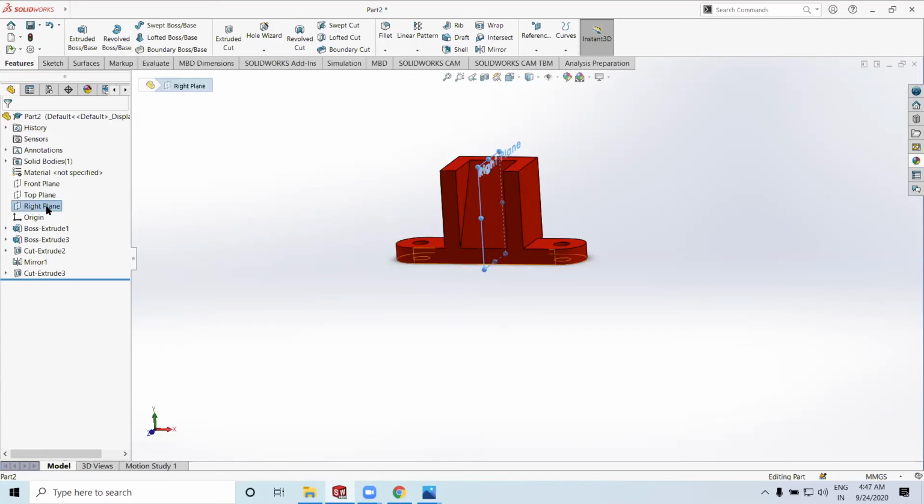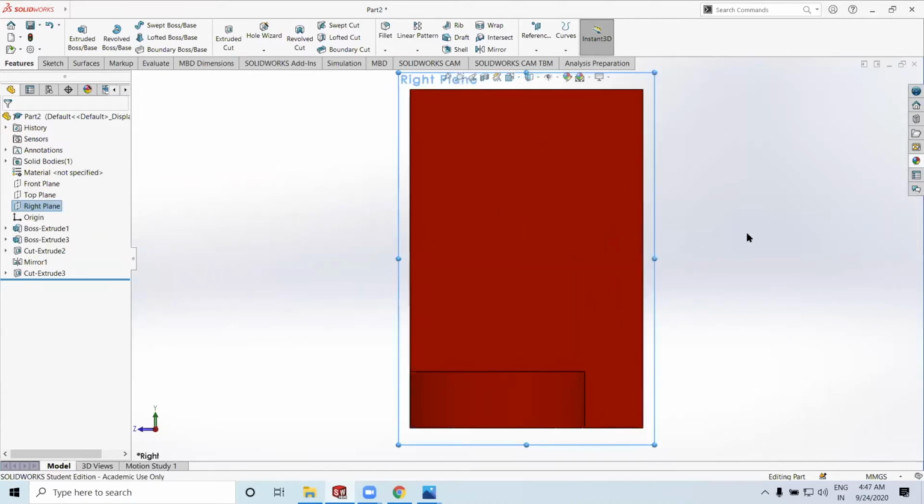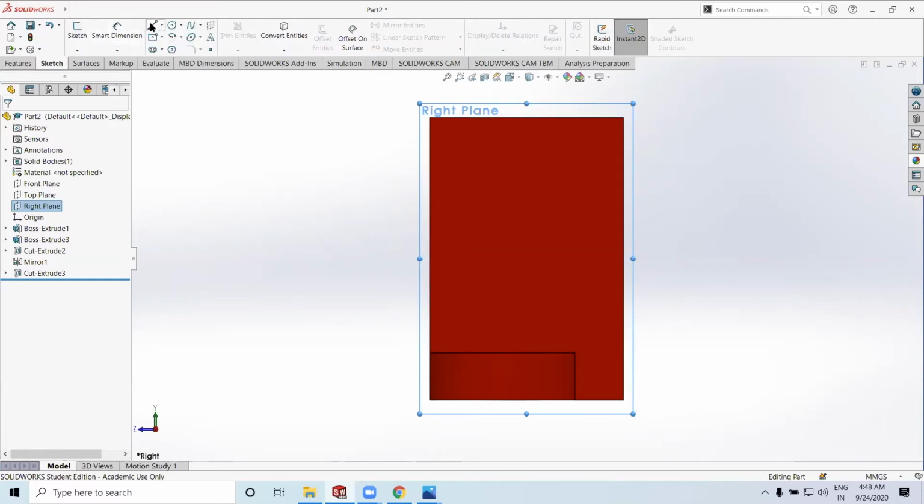We select that, then we select the sketch feature. I'll just show you how it's done. So it just changed this position. Now, what we have to do is select the line command from here. We select the topmost point from here and we bring it all the way down. And then we draw a triangular shape over here. If you're starting, we don't need to give it a dimension right now. When you create a right angle triangle, you close the shape.